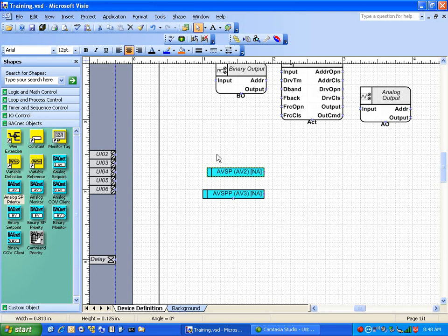I had a bunch of fin valves, and the customer didn't like seeing that fin valves were opening in the summertime when there's no hot water going. So the control logic really wasn't locking the valves out, and I needed a quick way to lock the valves out. So I said, okay, when the boilers aren't running, I'll just link to the priority array of the AO and kind of override them closed.